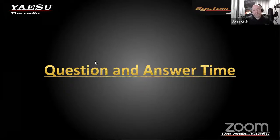One person asked, what is the general Fusion frequency again? It's 145.5625. Now, you may have to change the steps in your radios from 5 kilohertz to 6.25 kilohertz, but it's not that hard to do. Very simple on there.